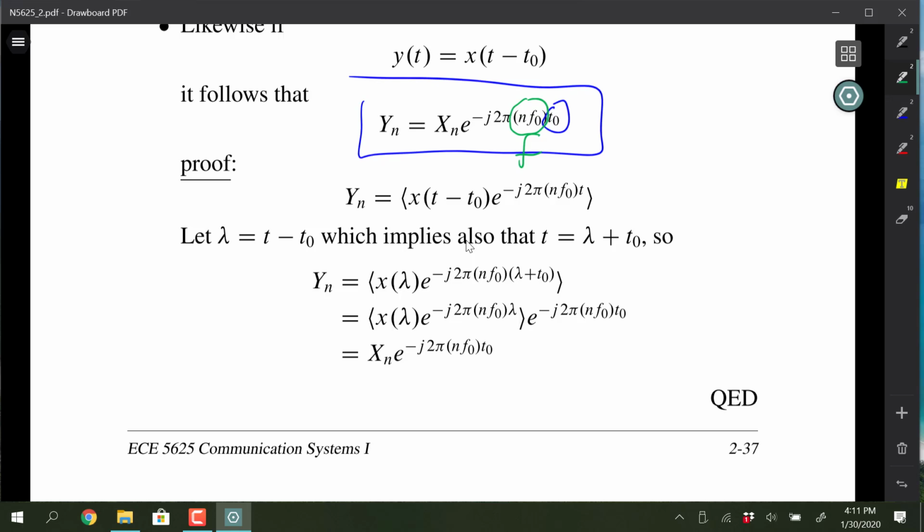Now, with that said, if we bring two periodic signals together, one arrives at 0 seconds and one arrives at a half second later or something, and they add together, but they're both the same periodic waveform, just arriving differently, then we're going to have constructive and destructive interference potentialities. We'll have a Fourier coefficient for the sum of these two identical waveforms, but then we'll have to use these complex exponentials to actually be part of the phase combining of the two signals. And then any amplitude that might be in there would be present. So I'm mentioning that because in multipath communications, that's exactly what happens.